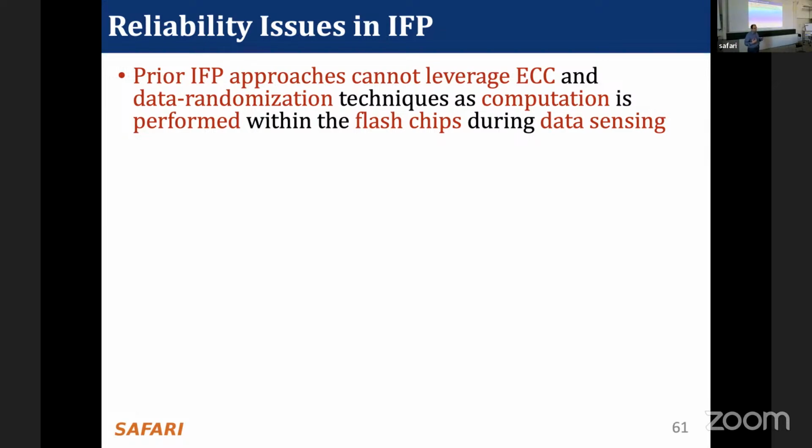There are some data patterns that can exacerbate the amount of errors. So we use that key and scramble data to avoid those worst case scenarios. And this is also good for security because there can be some malicious program that uses those data patterns to destroy your data stored inside the flash memory.